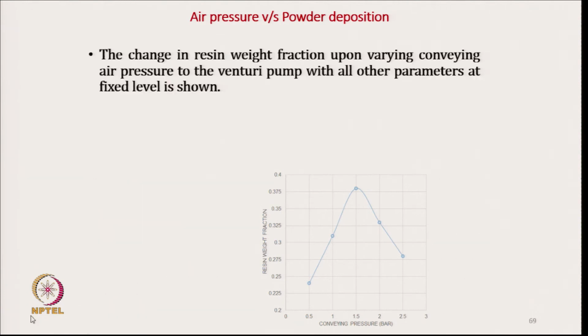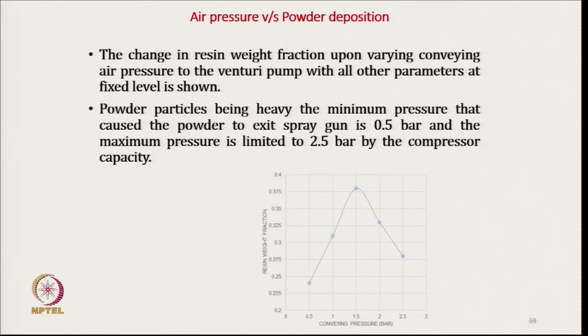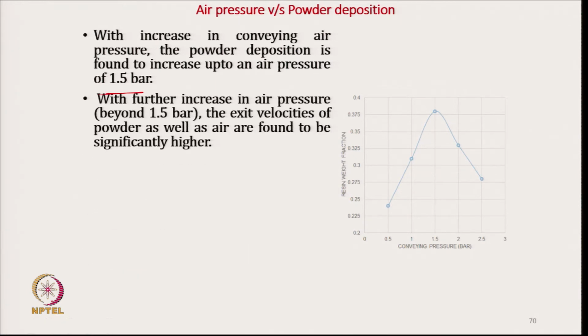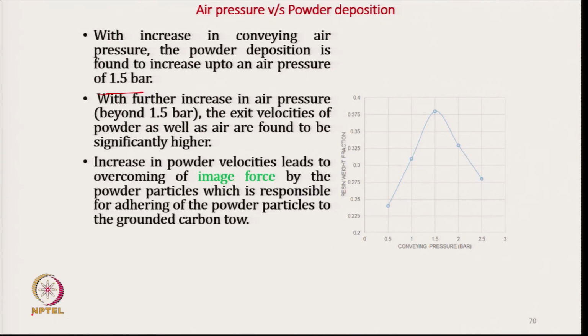So, this is attributed to the change in resin weight fraction upon varying air pressure. It is basically due to the fact that as we increase the pressure, the powder deposition is found to increase up to 1.5 bar, and beyond that there is a significant decrease.